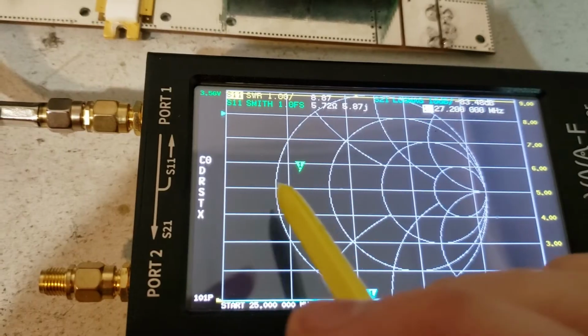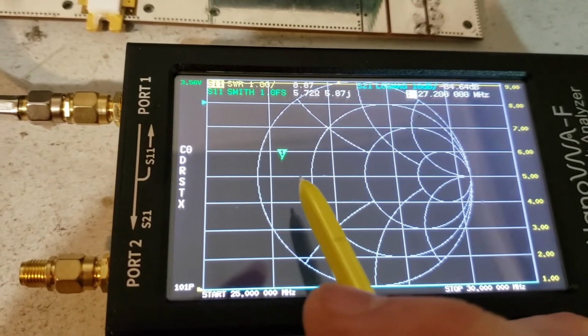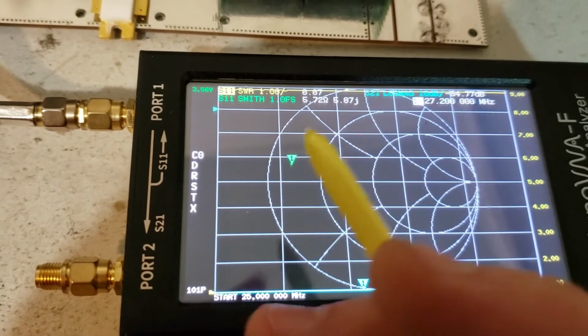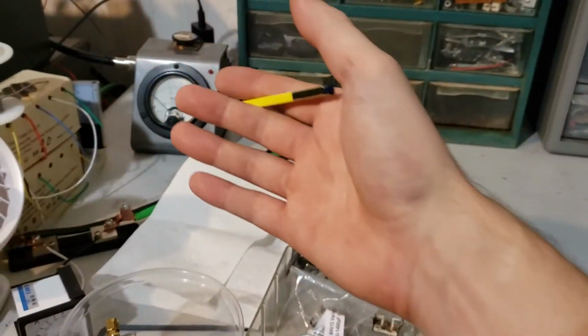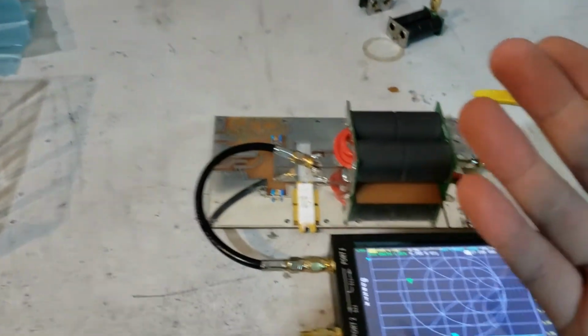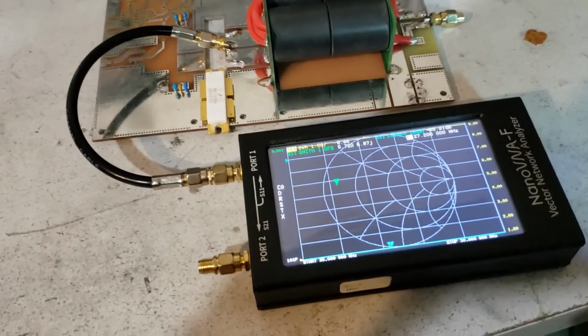Yeah, well, there's a point where your device just blows up. So you always want to start on the safe side of things and then slowly move your impedance down and check your amplifier, see how it's working. Take a look at it on the oscilloscope, the spectrum analyzer, the average power meter, the peak power meter. You have to take all these parameters into consideration if you really want to make a good amplifier, that is.